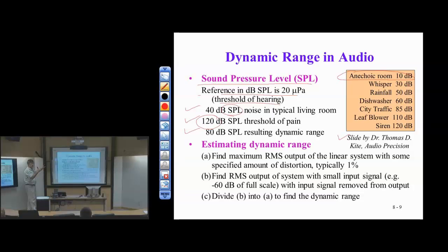Where's the problem? Quieter sounds. Because when it's very quiet, I have very few levels to choose from. I have severe quantization effects when the track goes from very loud to very quiet. Maybe I'm down to just 2 or 3 bits of what I can represent when it's really quiet. That's all I got. Good.